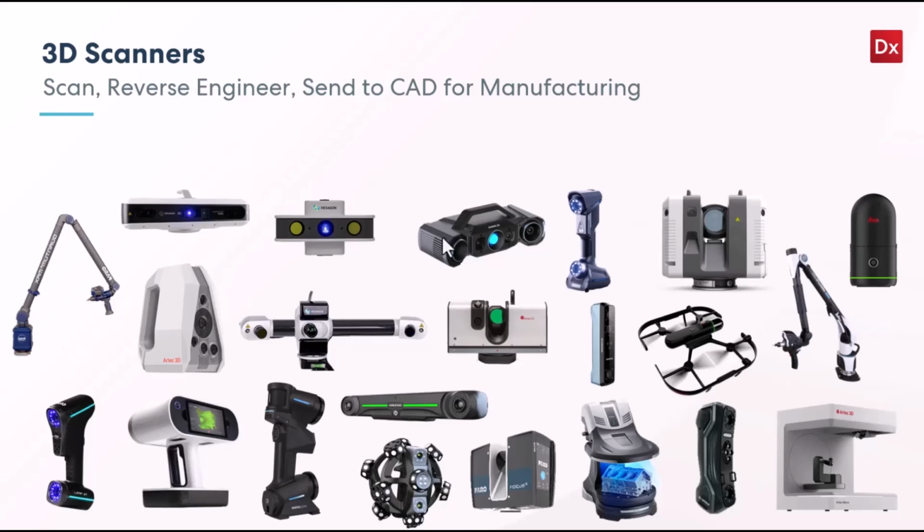So common extremes are the fact that this is a blue light scanner, so it's stationary, sitting on a tripod taking shots, and you would move it around or move the object on a turntable. Same thing with this one. Same thing with this one, where, with a handheld, you could move the handheld around it, and sometimes it's tracking itself based on targets that are on the object or around the object or on the ceiling or wherever. And you can see how this one would have advantages in certain instances, and these would have advantages in certain instances. A lot of times with the blue light, resolution and accuracy is an advantage.